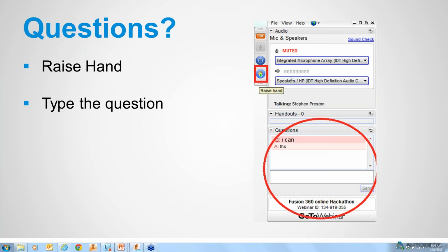That's what I'm guessing, that maybe these next sessions won't be big topics, but several smaller topics. And so this could be something we talk about in a little more detail. One of the places where it's used most often in Fusion is whenever you convert a T-spline back to a B-rep. When I leave the T-spline environment, those are all NURB surfaces that get created. And if I draw a spline in a sketch and I extrude or revolve or do something with that spline, the surface that's created is going to be a NURB.